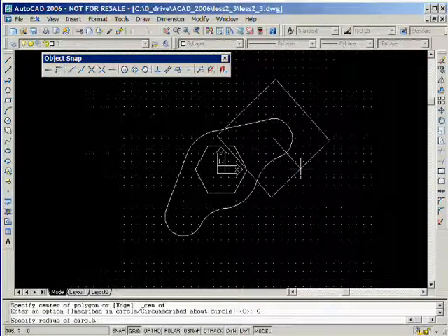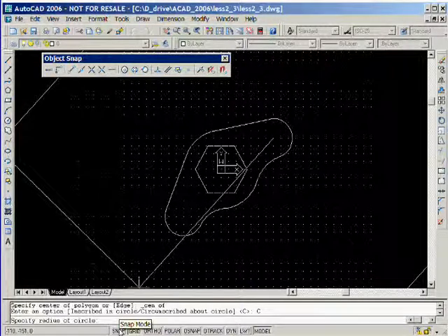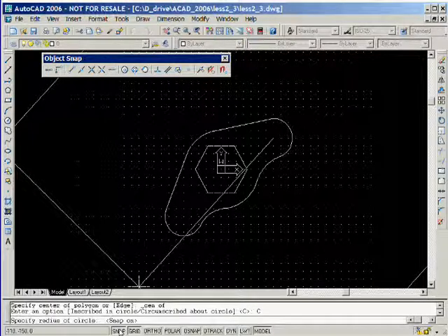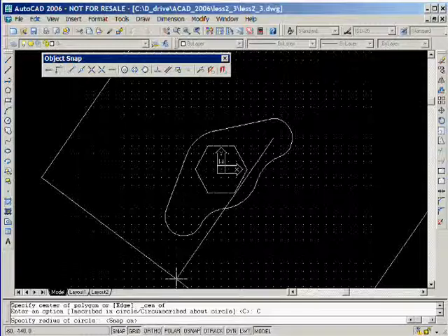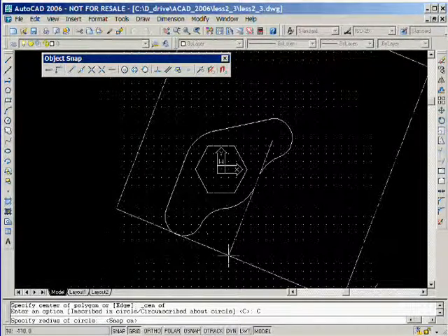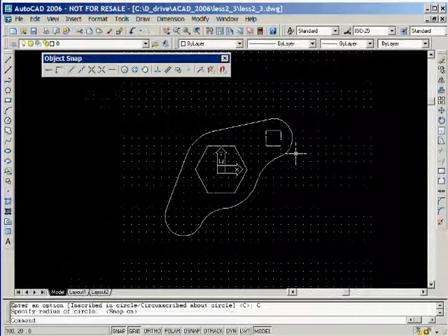Then click on the arc shown here after we see the center indicator appear. Next, we'll right-click the mouse and select the option shown here. Prior to indicating the location, we'll first turn on the Grid Snap option that is located in the status bar. And then click on the grid point that is just to the right of the center of the polygon.